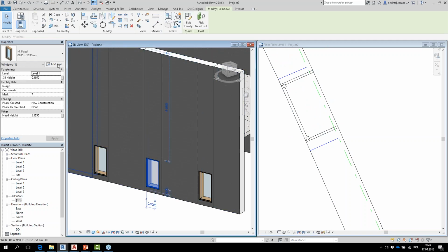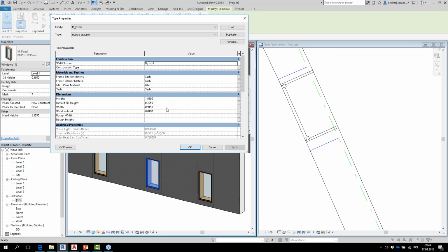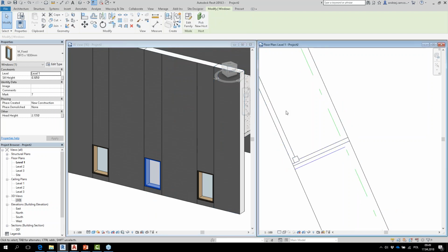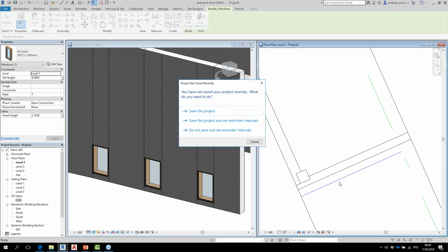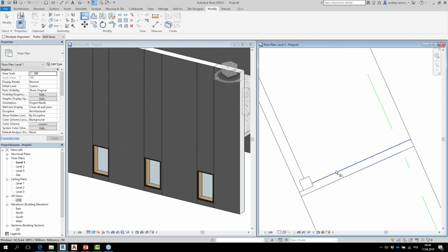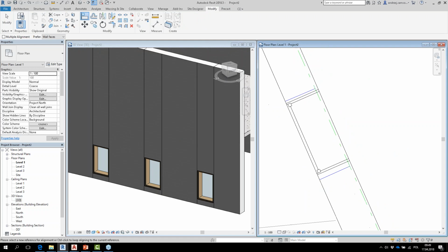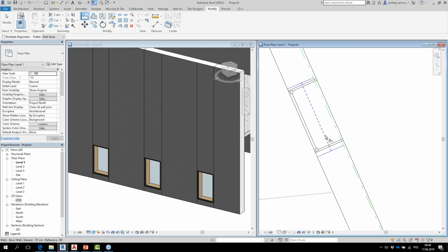These windows are all the same. It's the same type. Now I can change the width from 0.9 to 1.13, whatever there was, right? Apply, everything has been updated, right? All of them. Can you see that? And here I'm gonna just align again and align the window from here to here, so they fit perfectly into these locations which has been assigned.